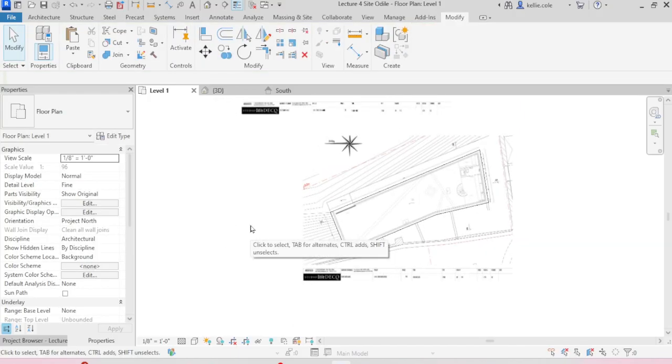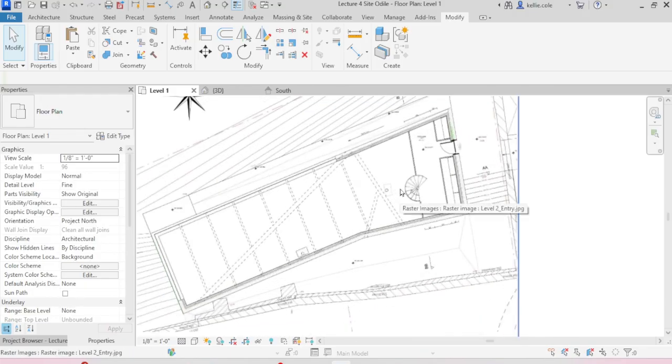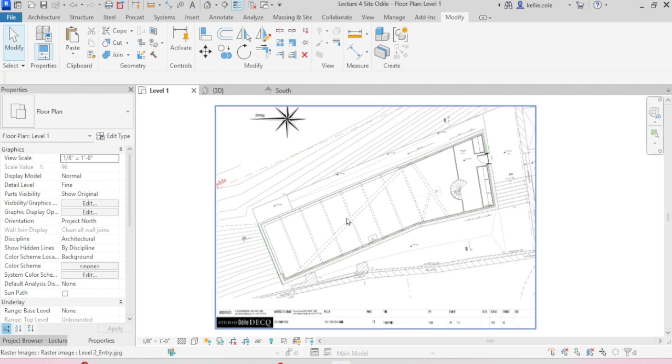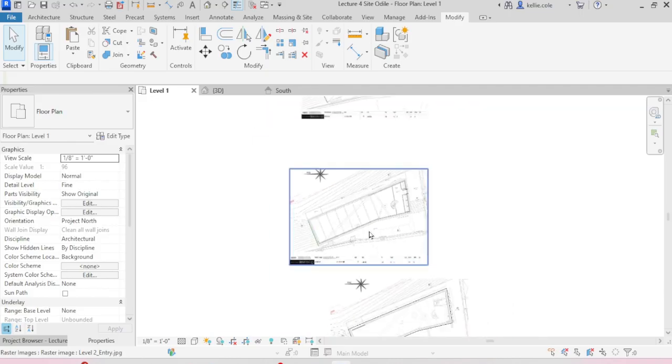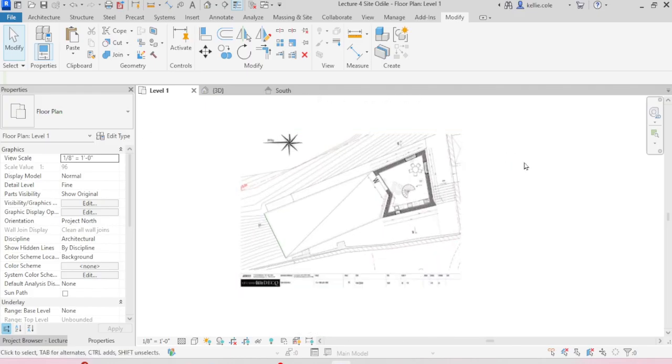As we build the next few levels, let's build them at 10-foot intervals. So from level 1 to the mezzanine, level 2, there's 10 feet. However, thinking back to our lecture, that is a 2-story interior volume. So we will extend the form that we've just created up to the 3rd level. But let's go into the elevation view of the south elevation in order to establish our levels.